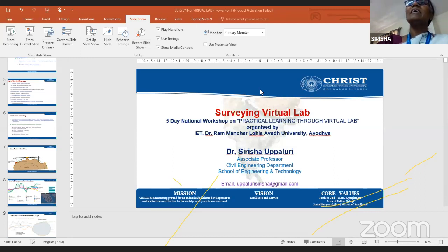Okay. Then I am going to fix my line of sight. Then what I am going to do, I should not shift the instrument to B. I have to shift my staff to B for the next reading. Understood? I am going to keep my instrument at the same place, telescope at the same place. Backsight as well as intermediate sight or foresight I have to take from the same position. Then only I am going to establish the relative elevation. The staff I need to shift to B position.